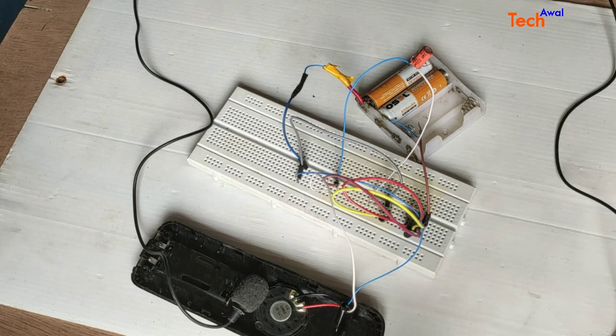Okay, so it is clear that everywhere it is the same. If I had connected a 10 microfarad capacitor, then two sounds were quicker, and then the third was very long, then again quicker, then the third. So charging and discharging happen through different resistances, and that much time gap we are seeing.